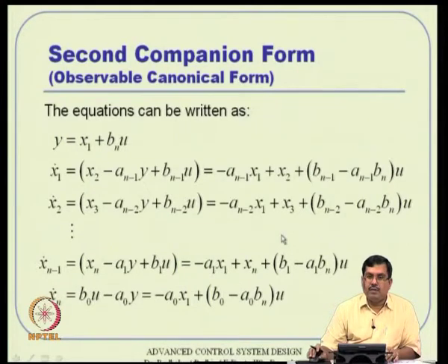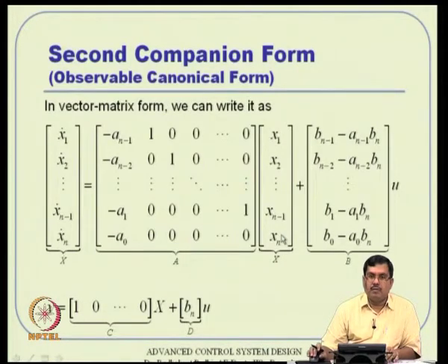So, then you can try to put that in the matrix vector matrix form. It turns out here that all these dots will contain x1 actually. That means this column vector is non-empty, all these column vectors will pop up. Instead of a row, what you get is entries in the first column. That is the difference between observable canonical form and controllable canonical form.